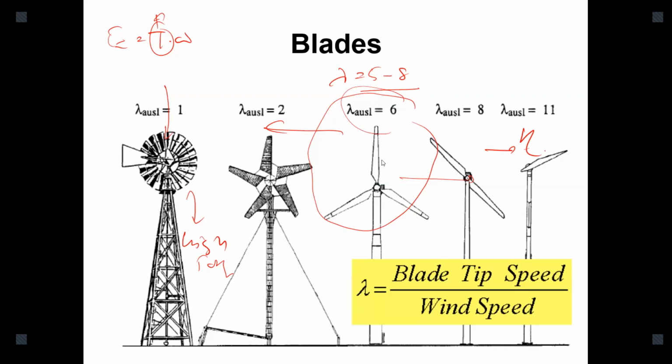But for a large wind turbine, this is not possible, because of the large masses on top the rudder cannot be used, because of the rotating mass. A large rotating mass cannot yaw quickly to the wind because it has a large moment of inertia. Then there's a common reason two-bladed wind turbines are not used for large-scale wind turbines.